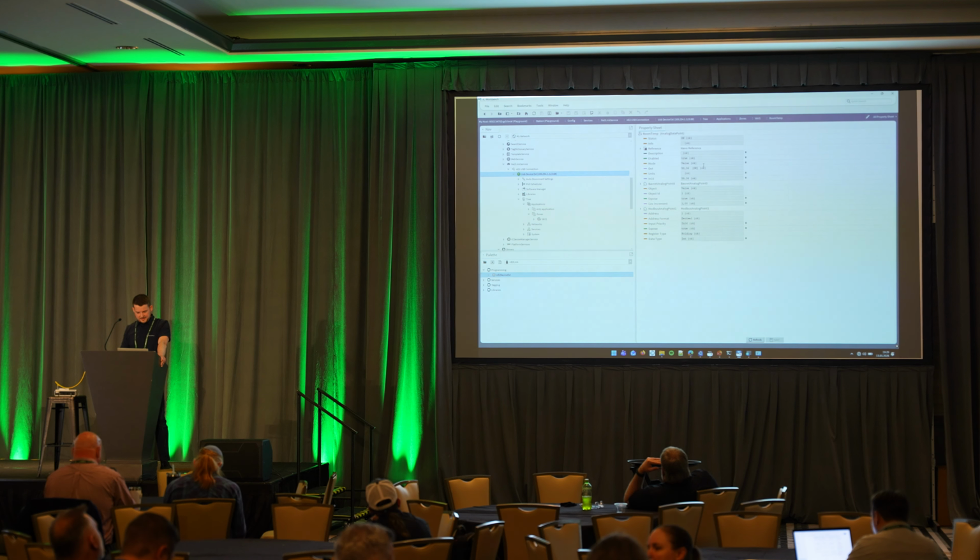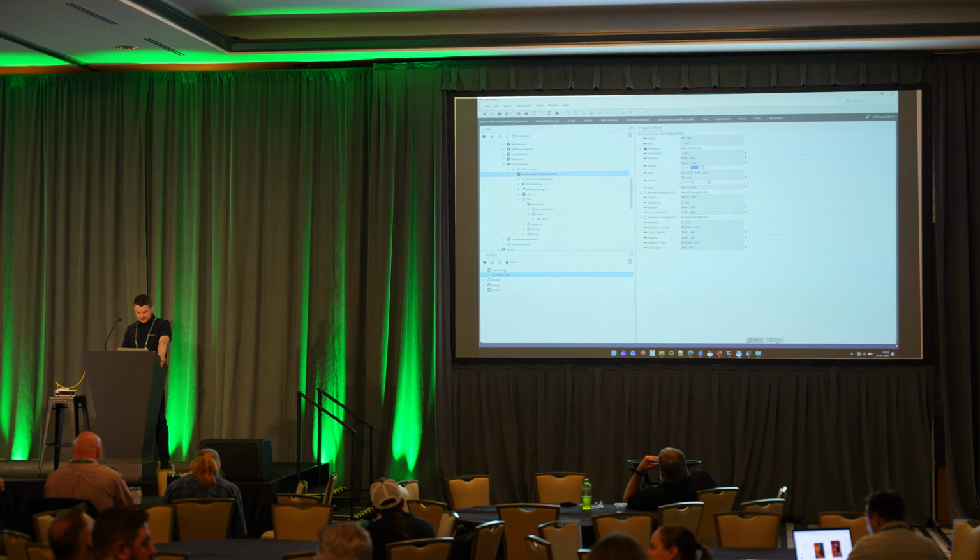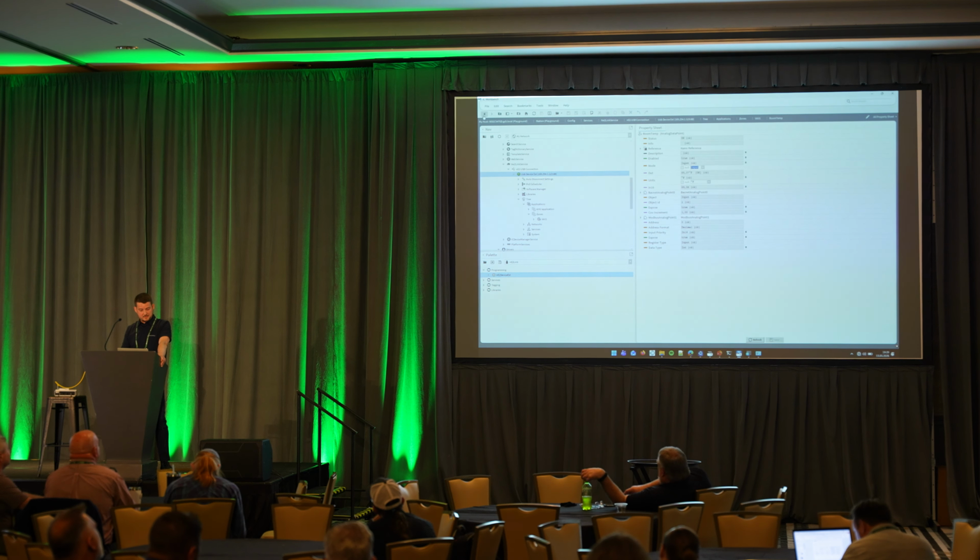So here we have the configuration for the point. We can set a unit. So let's select Fahrenheit. And now we can change that this is an actual input here. So now this point is going to also synchronize as a BACnet object input. When you discover that over BACnet, it's going to be your BACnet analog point configured as an input.